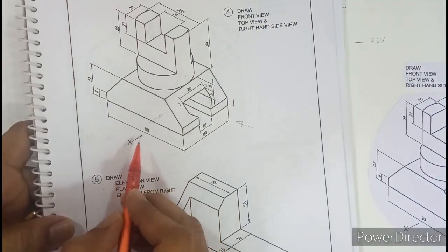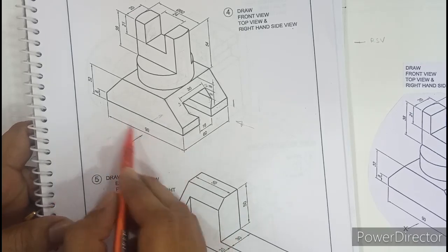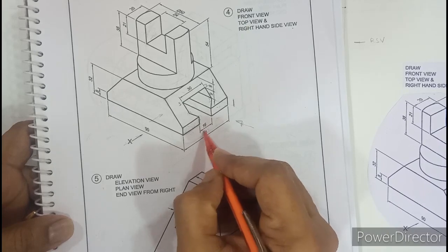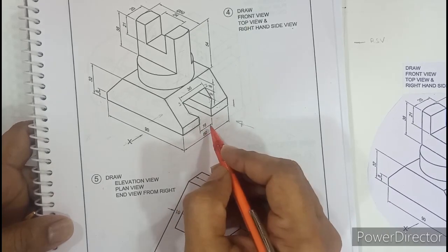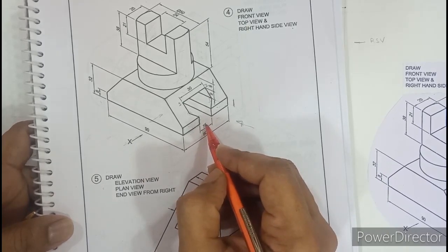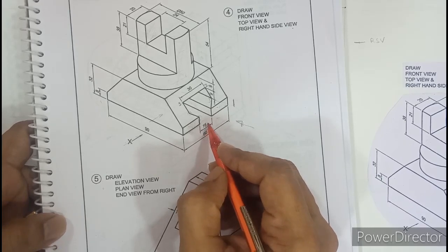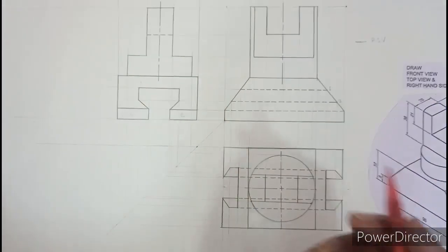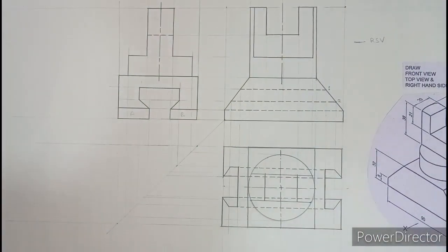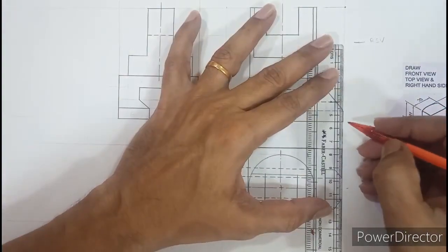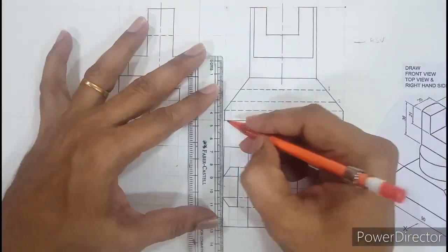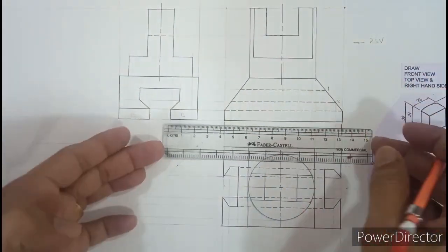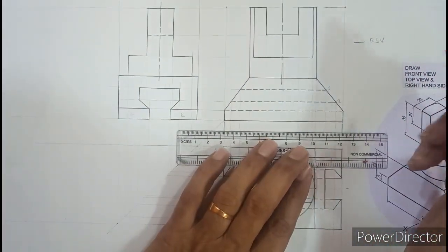So the first important dimension is the length, 90 millimeter. And along with that, while showing width 60, it is advisable to show 16 also. So remember, whenever you want to show 2 dimensions, one above, one below, always show smaller first, followed by the larger one. So we'll first show length 90. Length 90 can be shown in the front view. So here I will draw medium dark extension lines on both the sides, leaving a gap of 2 mm. And then from here we can show